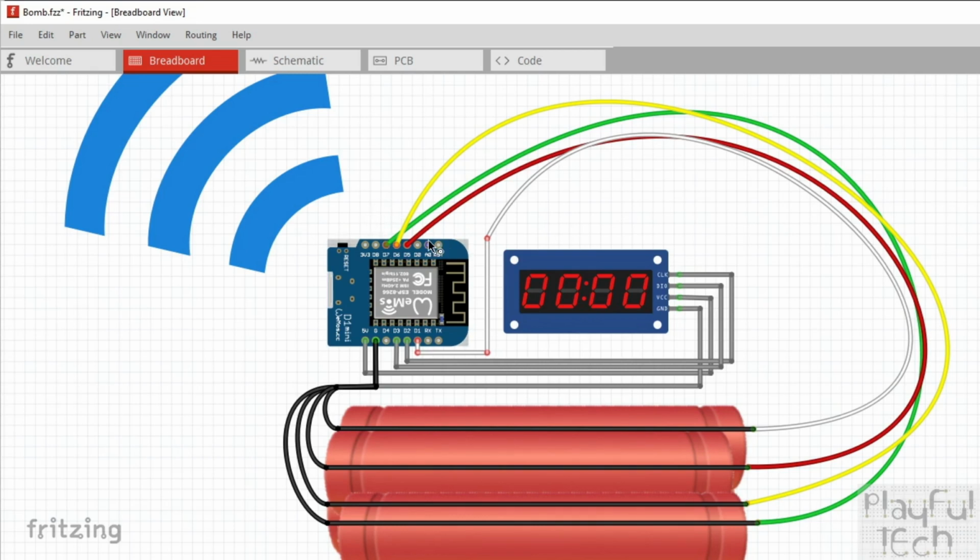So then I shifted them all this way a bit and used this D0 pin here, but I realised that that caused problems if the wire was connected when the board booted up. So on the third revision, I decided to use this D1 pin, and that's fine. This works just like a totally regular GPIO pin. It's got no additional constraints on it. So that's the reason why I chose that slightly crazy wiring.